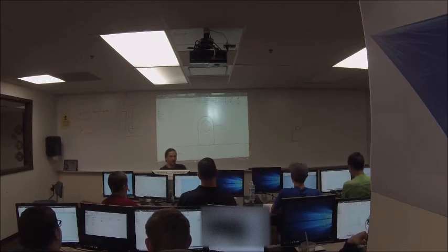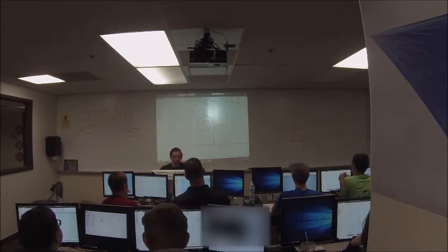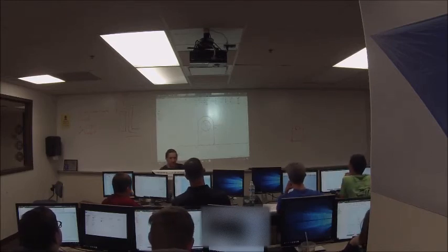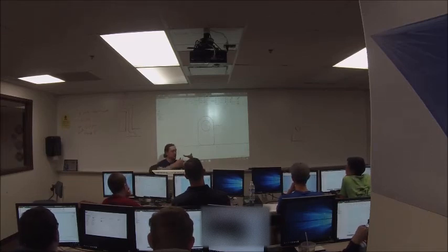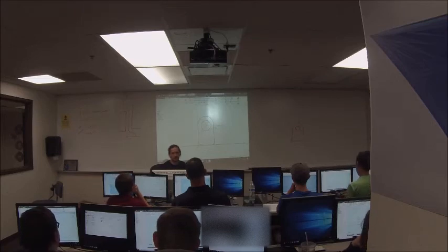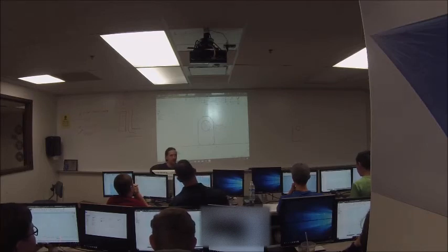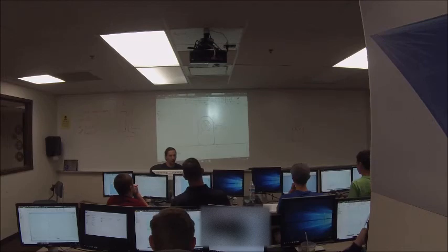If I click on another dimension, you see how it says D9 in here? Every dimension has a name. It's D and then a number. You can see I'm editing dimension D8 right now. So anywhere you type D8, it's going to take the value of that dimension and insert it. If you guys are familiar with programming, you know what variables are. This is a variable. If you don't know what that is, don't worry about it. You can click on a dimension and it'll place that dimension's name inside, and basically where Inventor sees D9, it's going to put half an inch.